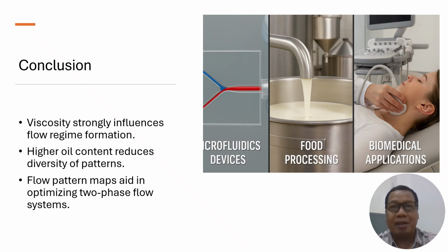Higher oil content, and therefore higher viscosity, reduces the diversity of flow patterns. The flow pattern maps developed here can aid in the design and optimization of two-phase flow systems in miniaturized applications.